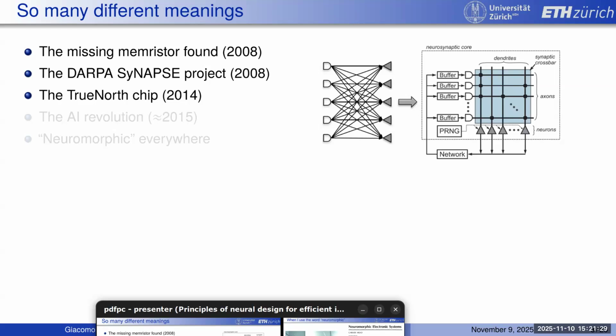I should also point out there is no clock; it's asynchronous. It just runs the equations as quickly as it can, and whenever it's finished, every core runs in parallel with its own self-clocked steps. Then every 1 millisecond, a manager synchronizes everything and sends the spikes from core to core to make sure that time in each core is aligned. Physical time is not considered here. This is a simulation, so simulation time can be much faster than physical time, or it could take hours to simulate a protein folding, which in biology would fold in a few milliseconds.